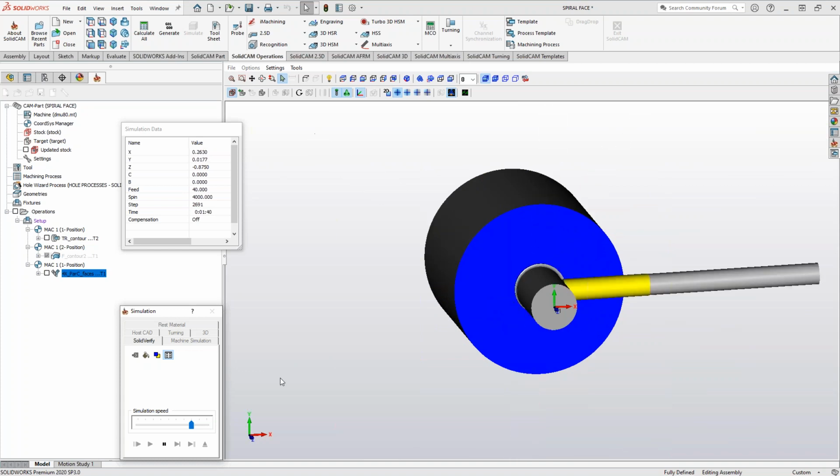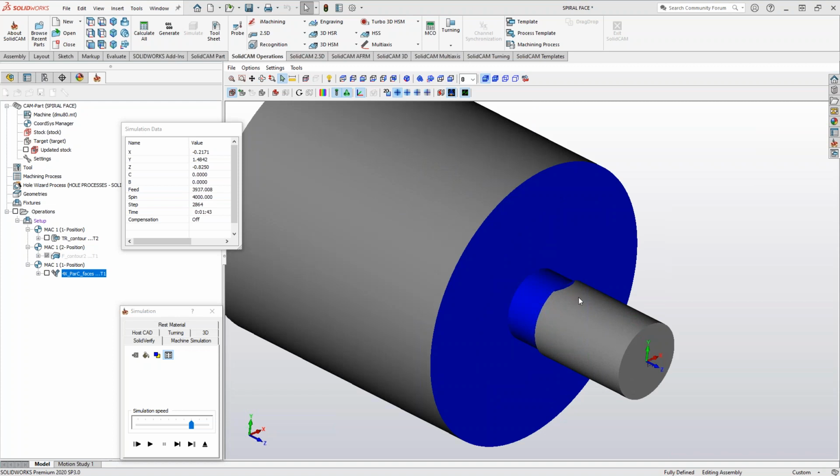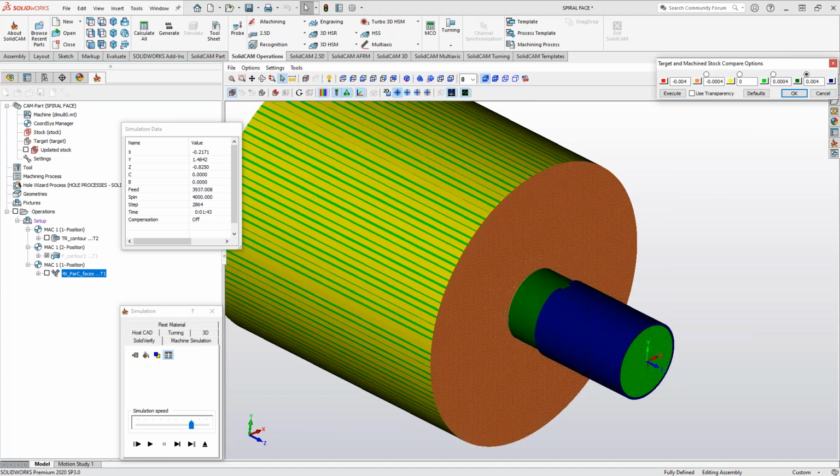This is a great toolpath for eliminating any witness lines or anything like that, just because we are in constant contact with the material going all the way through it. We're not doing a revolution, stopping, stepping down, arcing back in. So this will be a lot easier on your tool, but a lot better surface finish this way as well.